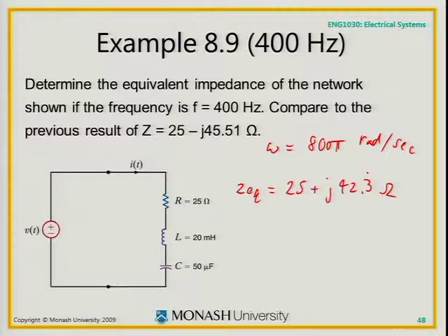At the resonant frequency, all I'm left with is R equals 25 ohms when omega equals 1 on root LC, and it must be somewhere between those two frequencies we've just done, because the first frequency it was negative j, the next frequency was positive j, so it'll be 0 somewhere in between. That is the resonant frequency for this particular circuit. So that's a series resonator. You can also have a parallel resonator where your inductor and your capacitor are in parallel, not in series.